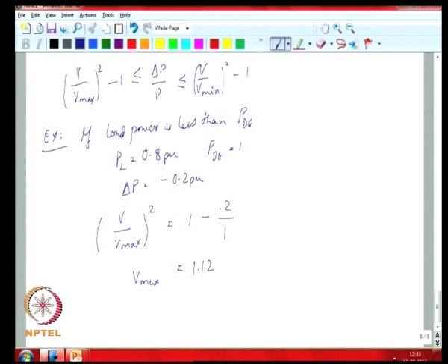So, if you had an over voltage relay at the DG which was detecting say 10% over voltage, at 12% over voltage it would immediately open your DG breaker and disconnect the DG. So, you would be able to detect a situation of unintentional island. Okay.